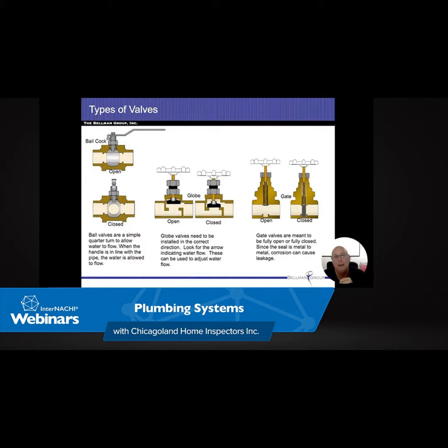I don't care what it is, cardboard, newspaper, anything that I can get a separation in between the two metals. Typically, somebody will put electrical tape on there. That works just fine, as long as they're not rubbing and we're going to deteriorate that electrical tape. But I've seen people put pieces of cardboard in there, anything just to keep the two metals from touching. And as long as they don't touch, then the electrolysis won't happen.